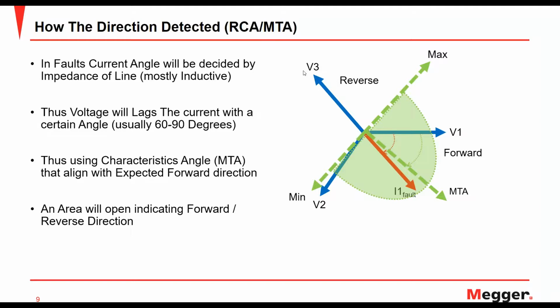Now, a lot of relay vendors and relay manufacturers use a similar concept to this. Some of them are making this area slightly smaller, creating a no operation area in the middle between the reverse and the forward, but that's not really a big deal for us, since in your relay configuration, you will either have a non-directional, a forward directional, or a reverse directional setting in your relay.